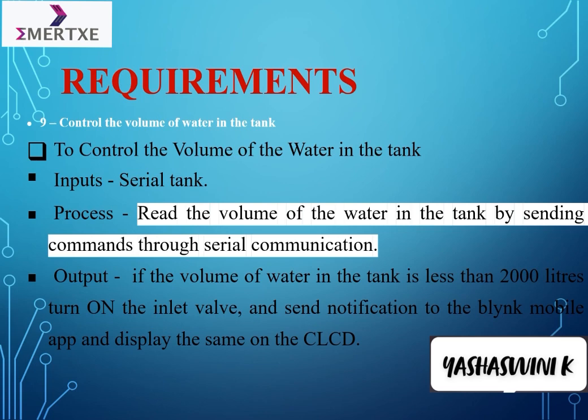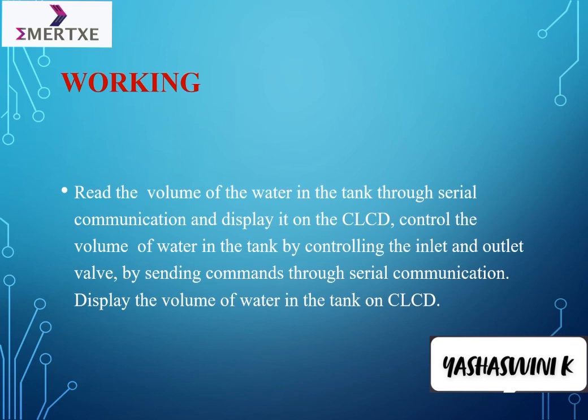So, working: read the volume of the water in the tank through serial communication and display it on the CLCD. Control the volume of the water in the tank by controlling the inlet and outlet valve by sending the commands through the serial communication. Display the volume of water in the tank on the CLCD.